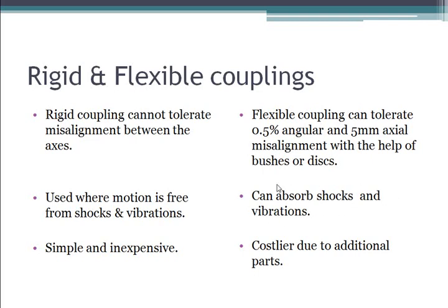Next, the design is simple in rigid couplings because there are fewer parts, and the cost is less compared to flexible couplings. Flexible couplings have additional parts like bushes and discs, so they are costlier compared to rigid couplings.